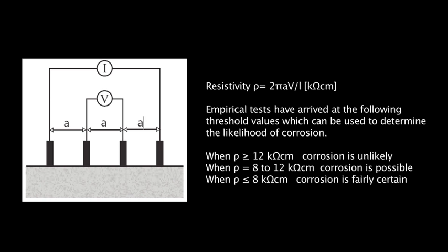Another major influence on potential measurements is the electrical resistivity of the concrete. Low resistivity leads to more negative potentials and the potential gradients become flatter. Higher resistivity leads to steep gradients, and the measurement grid must be made finer in order to avoid the risk of missing an anode. It is therefore very important to measure the resistivity.